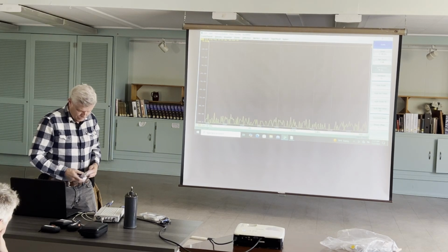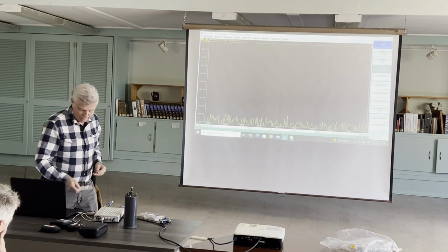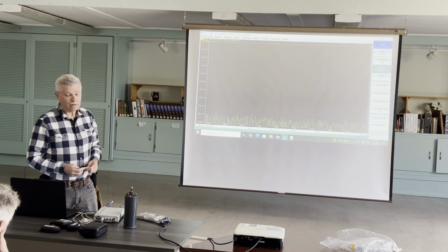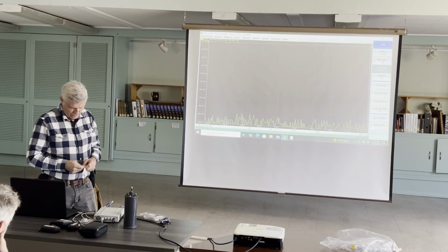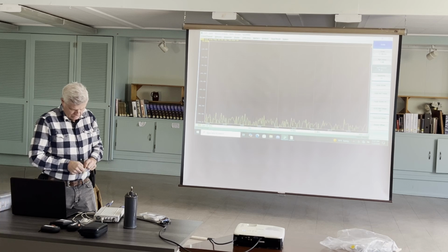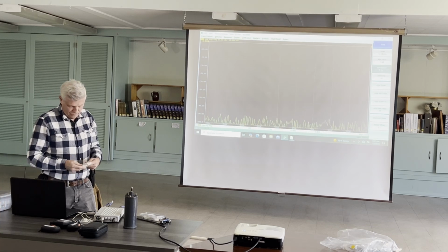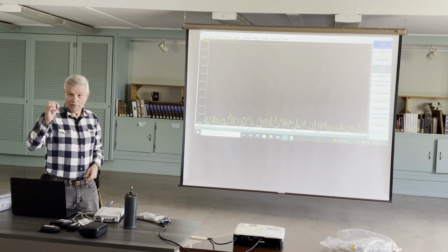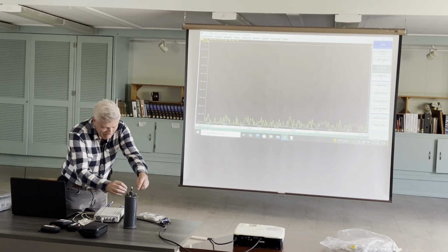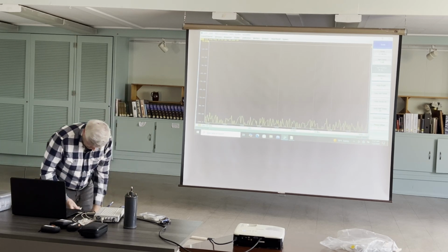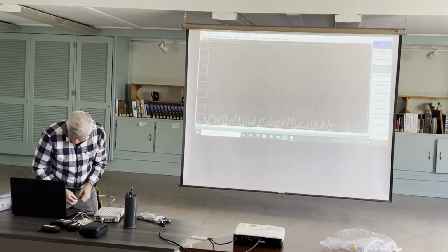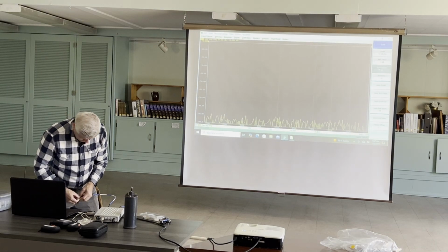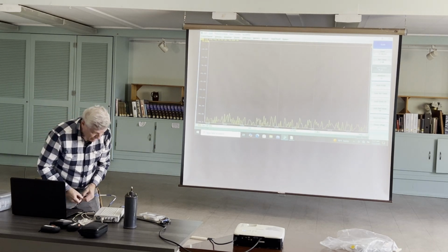So we're probably going to introduce, my guess would be, about 1/10 of a dB of amplitude error. There's probably very little phase shift in these, but it depends on what you're doing. If you're up in the microwave range, if you're measuring 27 gigahertz signals, well, then there's phase shift in this. Let's put these on first. Now I'm going to change the stimulus again. Well, let's start with where it is, and then we'll move it in.